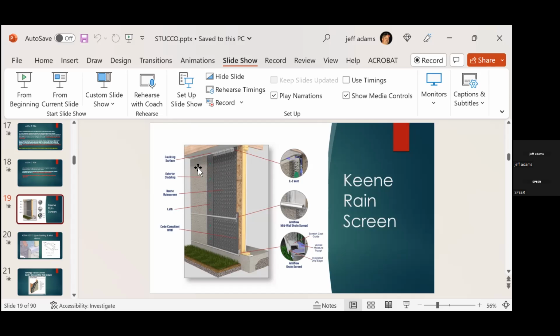This drawing had to be shrunk down a little bit so you can't see the detail of the wording as much, but it's a whole process of a vent skin system. Their product, if you remember, was required to be 5 millimeters. This product is actually 6 millimeters, so it definitely covers it. It gives you ways to terminate your flashing details at expansion joints or control joints, and an intake up here. So we're really basically pulling air up the wall and out through this venting system that terminates up here. It can be sealed and caulked up here, and there is a way to do it, but they have an actual vent skin system that just literally draws the air up.